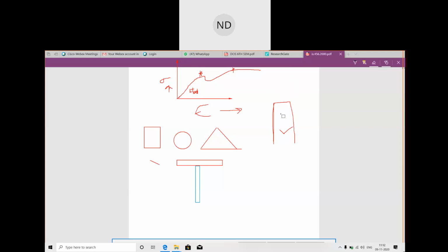Why are we doing plastic analysis? Because it is quite rapid and also a rational approach for analysis of structures. It also controls the economy regarding the weight of the steel, since the sections required by this method are smaller than those required by the method of elastic analysis.